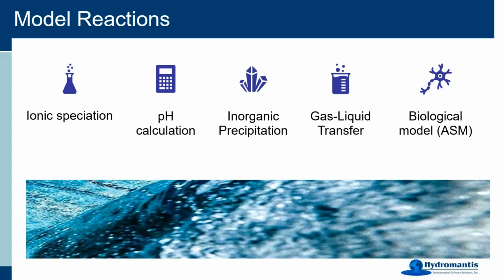So what are we doing here? Basically, we are doing ionic speciation for all the compounds that are dissociated in water, like weak acids and weak bases. All of those have temperature dependent dissociation constants in the model, and based on those values we identify the ionic speciation in the system. We do a very detailed calculation for the pH, including all the speciation of the ionic species. Then we solve algebraic equations, and we have a very robust calculation method to estimate the pH.